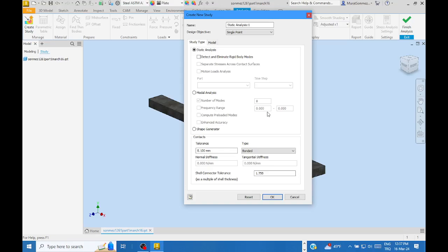If you know that the resonance frequency corresponds to 2000 RPM, never select that motor. It is quite an important and a little bit sophisticated topic to deal with. But today, using the software, you can determine resonance frequencies quickly, even in a few seconds. If that is the case, then select the modal analysis option.